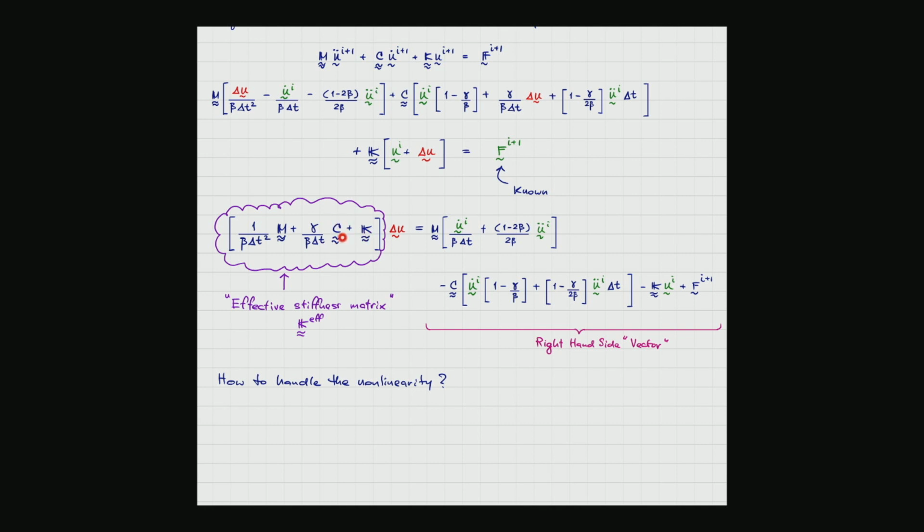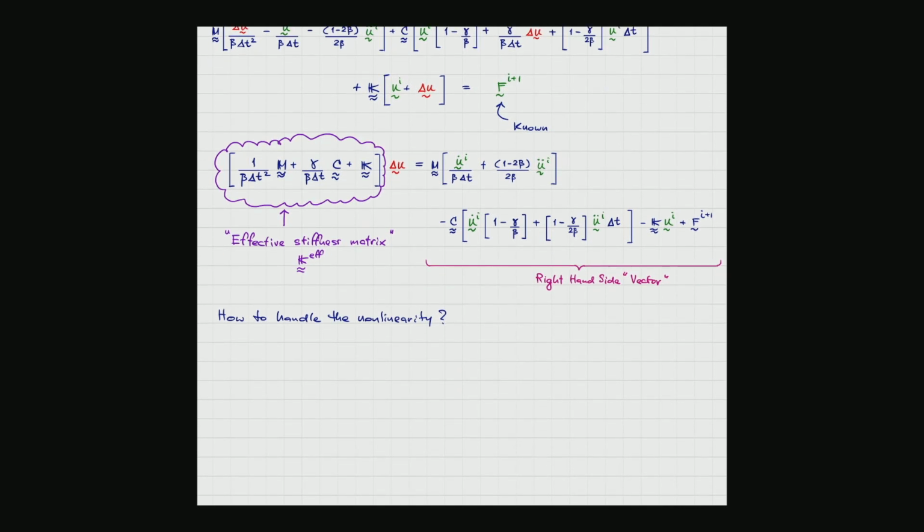As for c, if it is just a dashpot with constant damping, c is not supposed to change, but if c is changing, then you might end up with a nonlinear problem. And the mass matrix is generally not changed. The mass is always there, coming from the calculation of the contribution of mass to a given node.